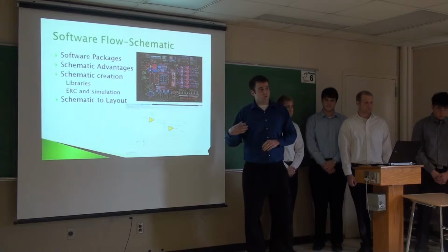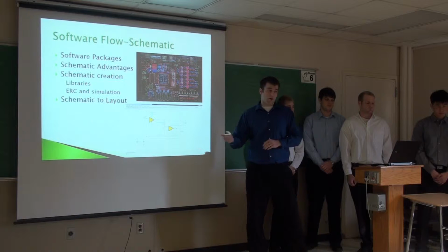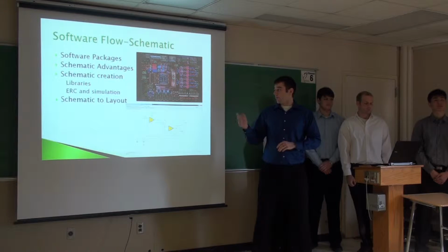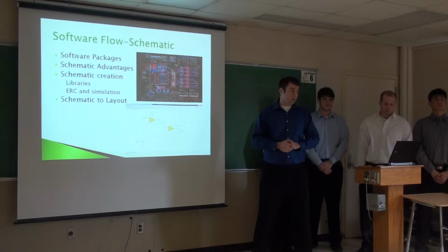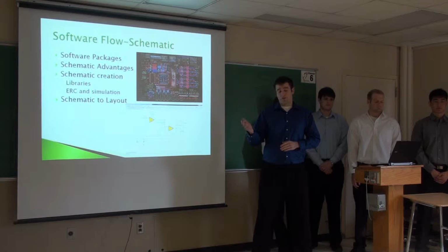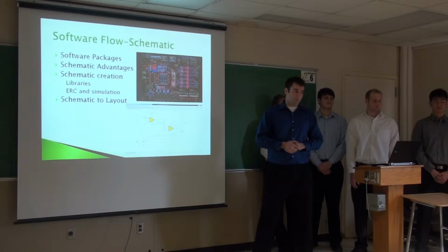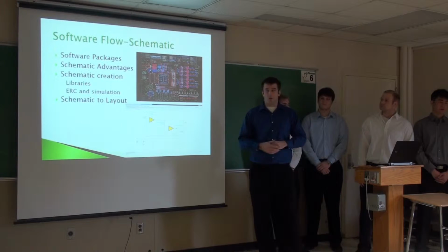So it makes it easier to share your design, tell people what your printed circuit board does. It also makes it easier for you to check your routing, make sure you have all the routing correct. And schematic editors actually have a lot of simulation tools available. So you can build your schematic, simulate it, make sure it works correctly, and then if it does, you move on. If not, it's really easy and really quick to change the schematic, whereas once you're in the layout, it's a lot harder and it's more time consuming. So it can save you a lot of time down the road.